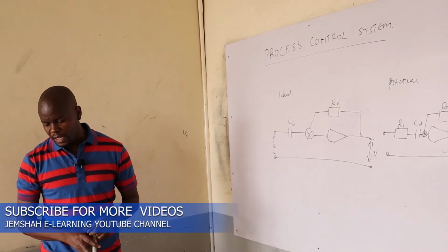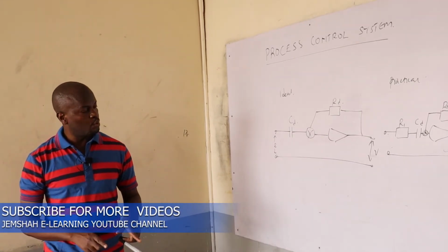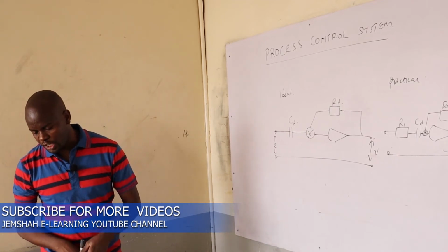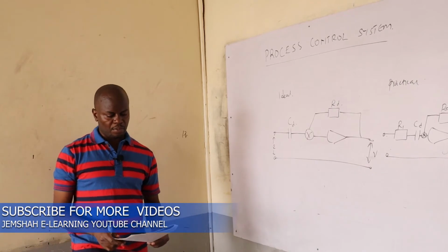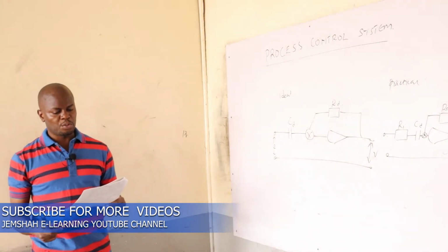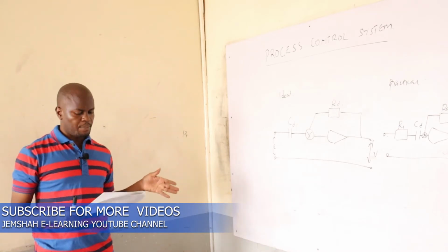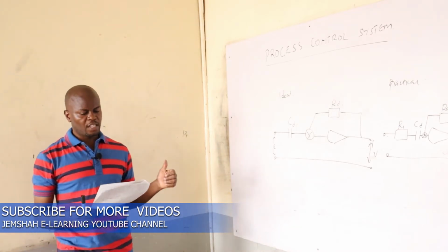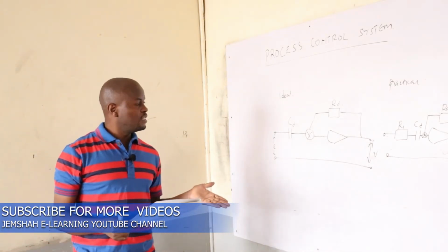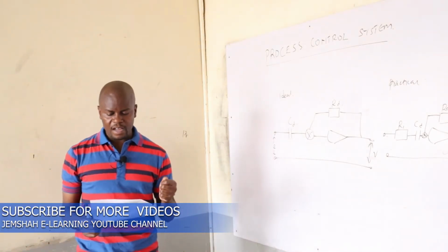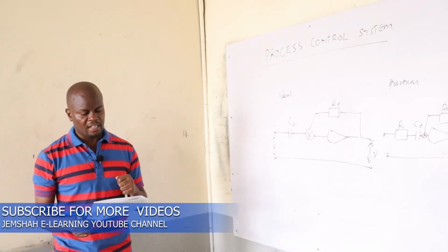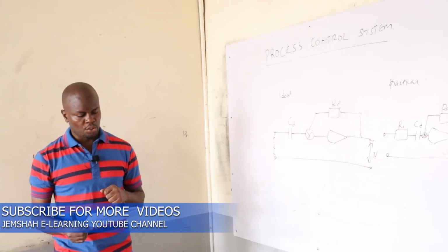And the same proportional control will eliminate the oscillations that occur as a result of integral control. So it is always used in processes with large load changes, where the proportional mode alone is not capable of reducing this particular offset to an acceptable level. The integral mode will provide the reset action by constantly changing the controller output until the error is reduced to 0.